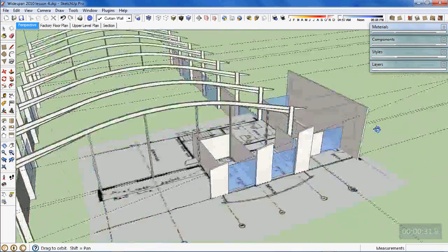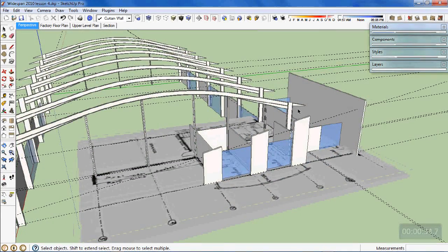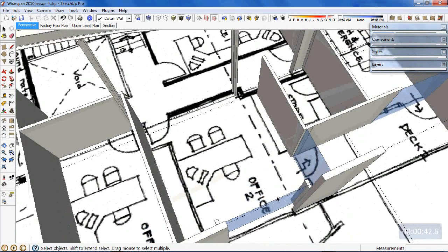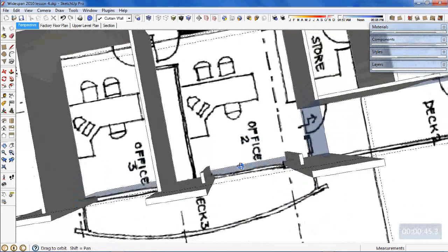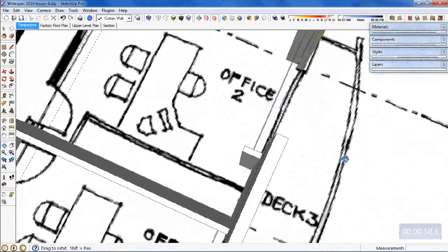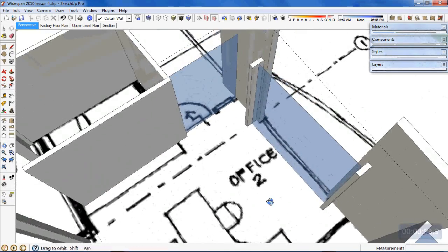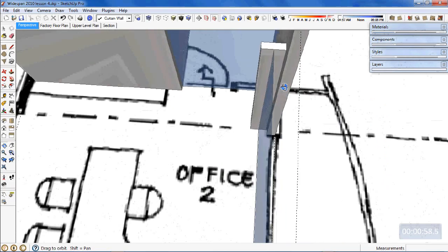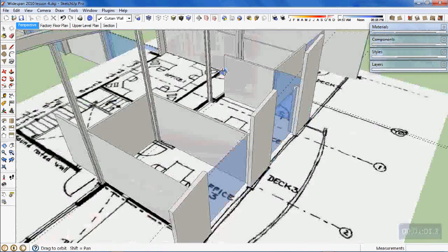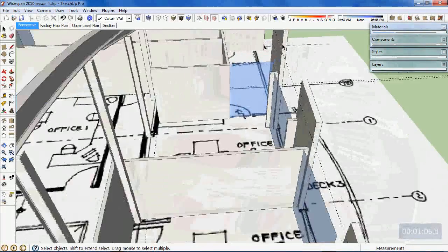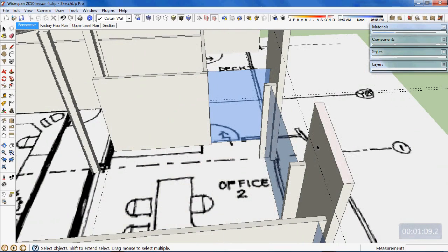So the next thing to do would be, and in doing those glass curtain walls too, I'll show you what I've done here. I'm not too sure if this is going to be the final solution, and I haven't determined a solution over on the other side yet, but I've created these little nib walls so that the glass curtain wall can be set back a little bit, because these concrete tilt-up walls in the front here become parapets in front of the roof. The roof will finish in behind, on the back surface of those parapets.